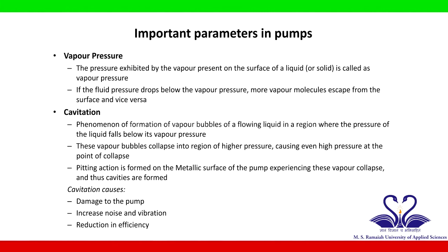Cavitation is an important phenomenon wherein vapor bubbles of a flowing liquid are formed in a region where the pressure of the liquid falls below its vapor pressure. These vapor bubbles collapse into region of higher pressure, causing even high pressure at the point of collapse.